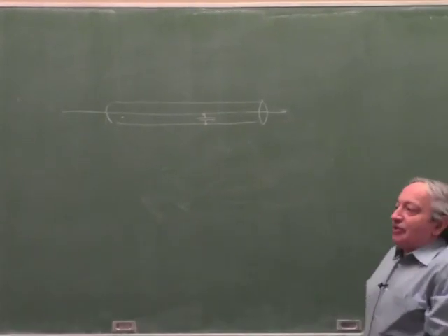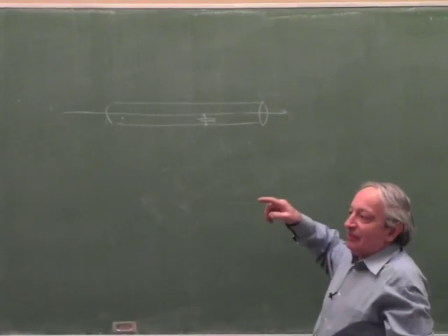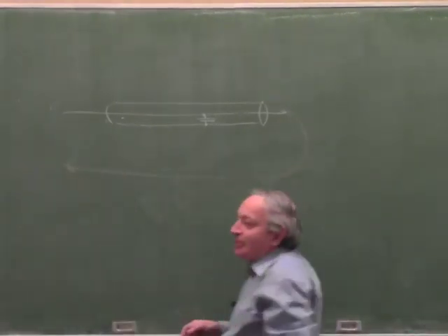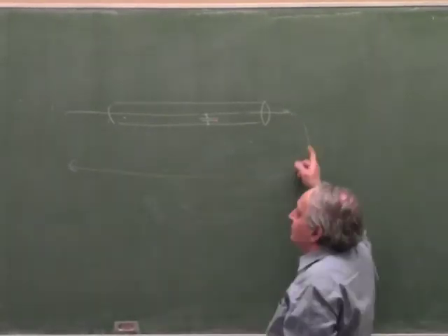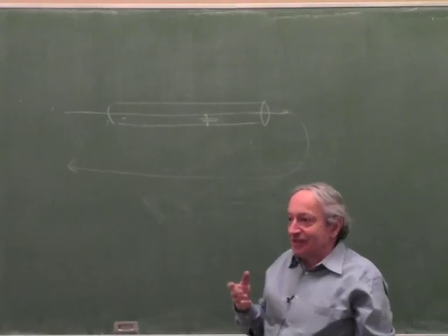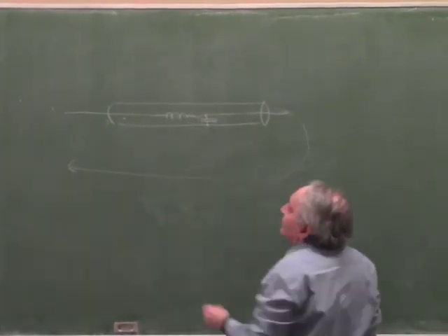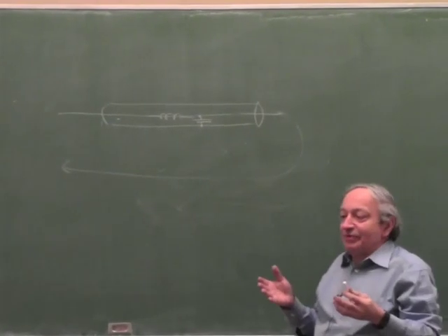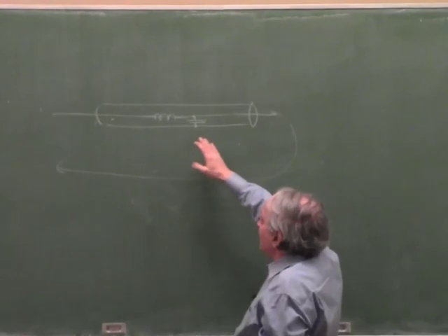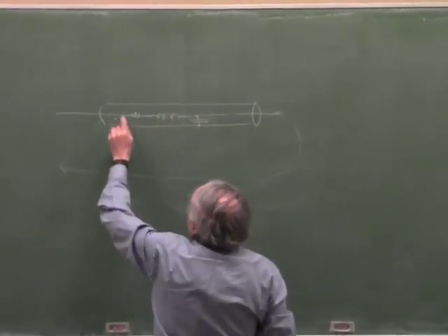There is also parasitic inductance, because if current flows through a wire, the current has to return somehow, and that creates a loop, which means there is inductance. It's not obvious when you look at a wire. Why would a piece of wire have inductance? But it has. Even if we ignore that, there's also a bit of resistance.